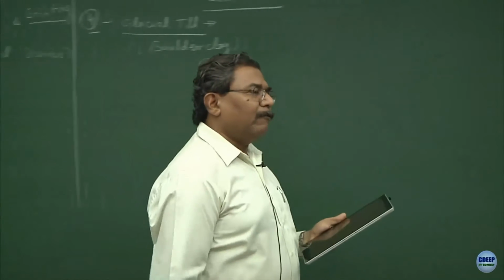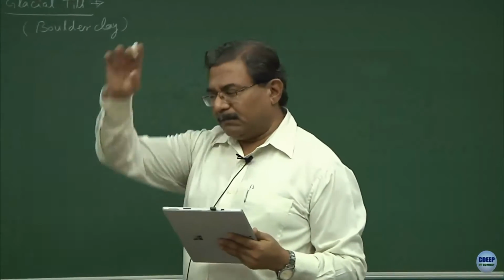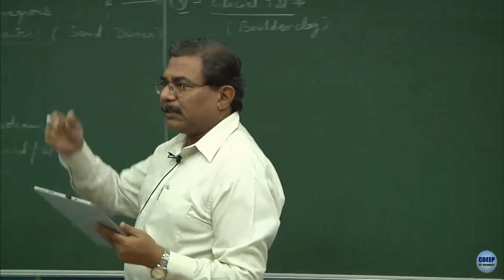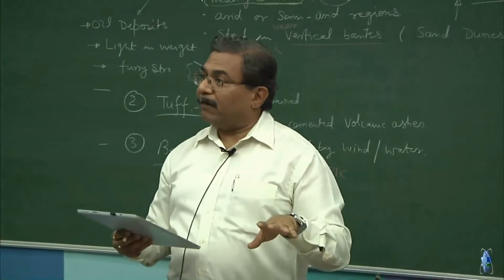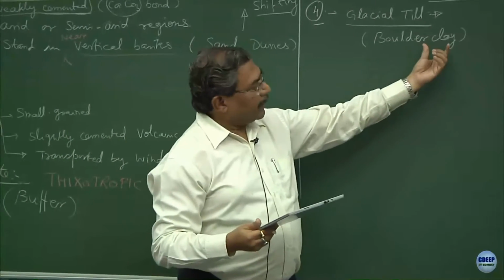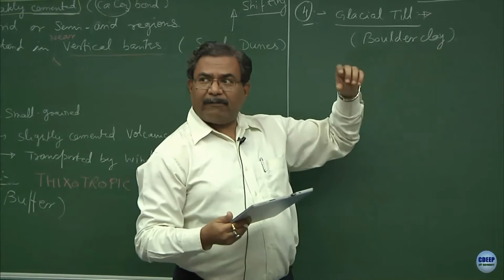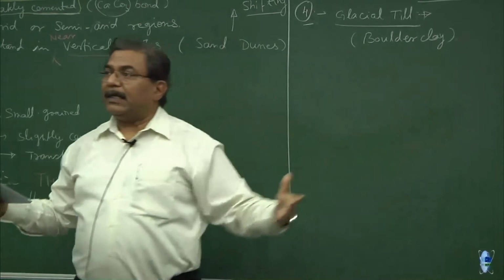Those of you who come from Himachal Pradesh in particular, or maybe upper reaches or lower reaches of Himalayas, you will realize that the big difficulty there is to lay the foundations. Why? Because these type of materials have a combination of a clay fraction, which is very fine particle, and boulders which are very big in size.